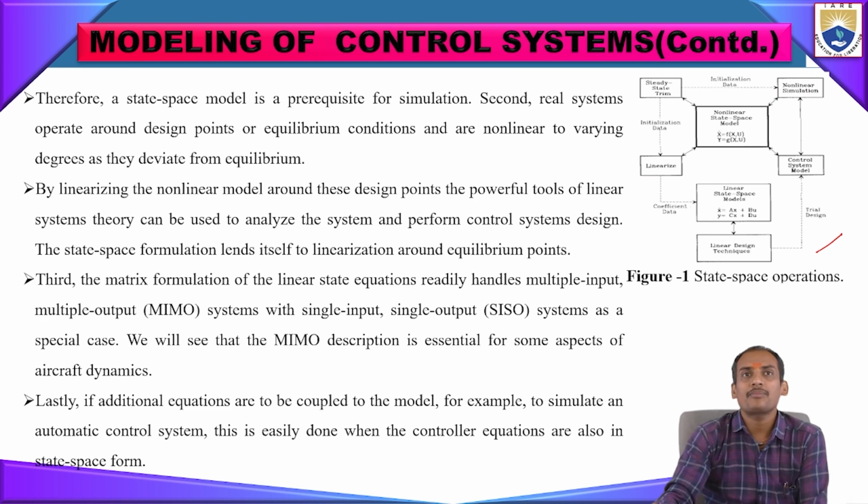So here, the state space model is a prerequisite for simulation. The real system can operate around the design points that are the equilibrium conditions and are non-linear to varying degrees as they deviate from the equilibrium condition.